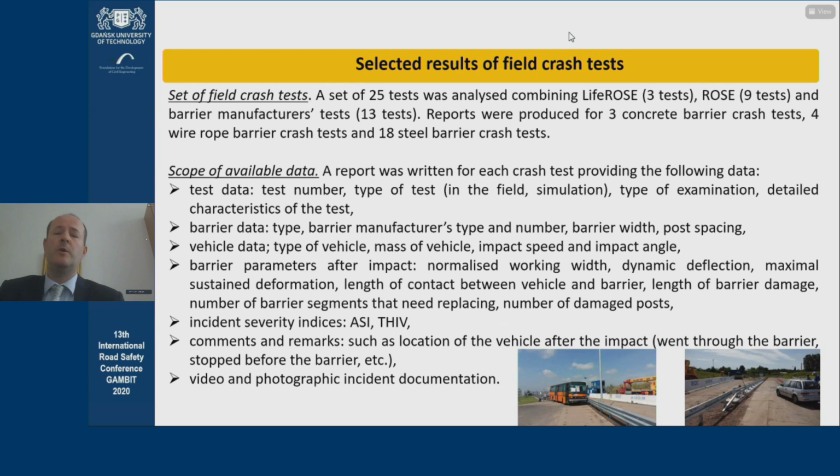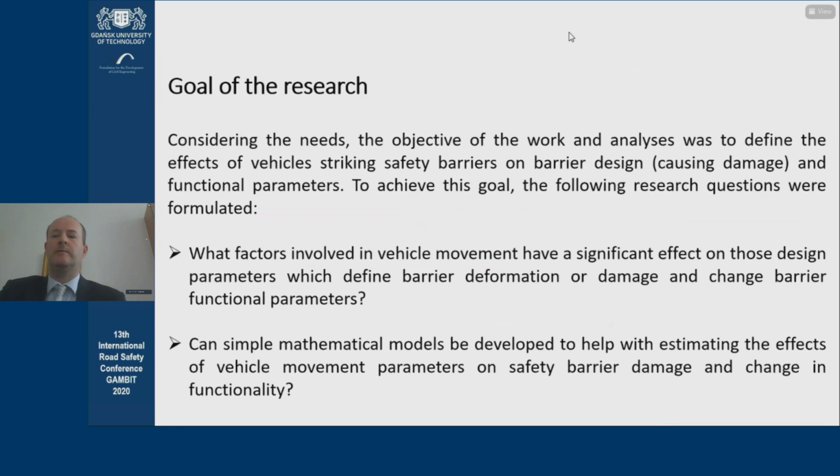So dynamic displacement, the depth of damage, the number of damaged posts, segments that needed replacing. We also looked at the severity of the incidents, ASI and THIV. And of course, we compiled photographic and video documentation.